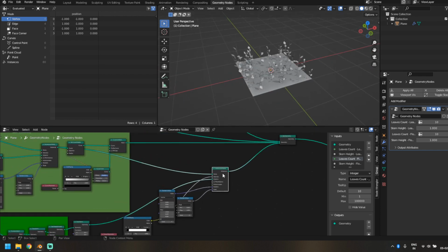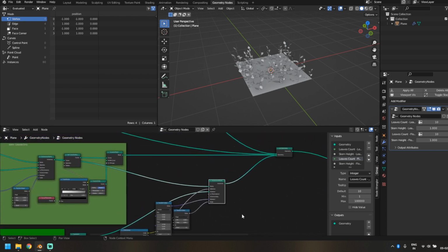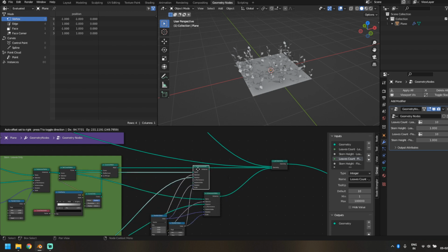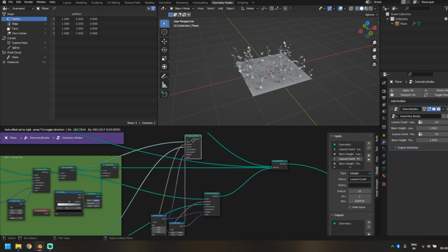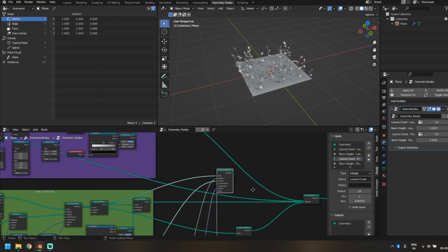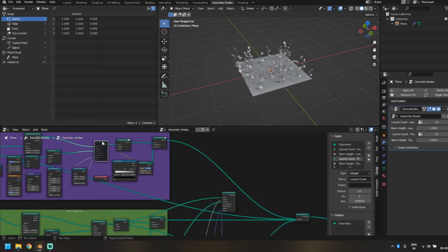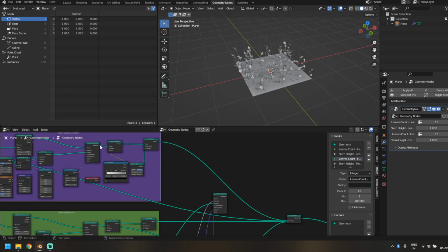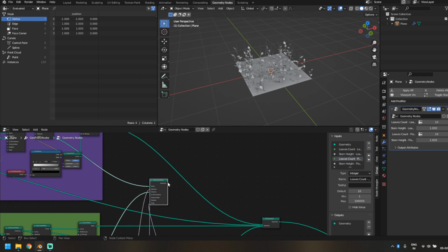So we also have to create the same node at the top as well. So we're going to use pretty much the same values, right? And so we can just simply do Control, Shift, and D. So as soon as we do that, all the connections stay intact, but it just creates a duplicate of the original node, right? So let's come back and let's unmute this. So we'll connect this geometry now to instance on points. Now this is basically our stems with the flowers, right?